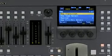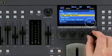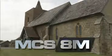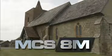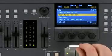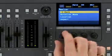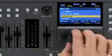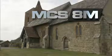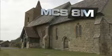There is one keyer available in the MCS-8M. This can be either luminance, linear or chroma keyer. All can be used as video keys or self keys. Whichever key type used, it's possible to make use of the built-in resizer. To use the resize function, select keyer, resizer, location, and move the XY size parameters. The key can be zoomed, moved horizontally, vertically, or even be given perspective.